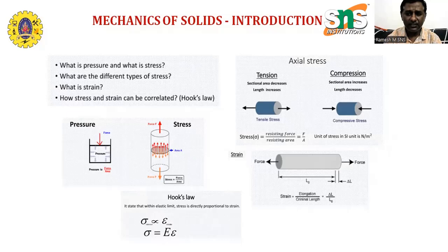So what is the stress in materials? It is nothing but the resistance offered by the body to meet the load. How much force is acting on the material and how it responds over the area contacted, that is called stress. The unit of stress is Newton per meter square, based on the mathematical relation: force divided by unit cross-sectional area.